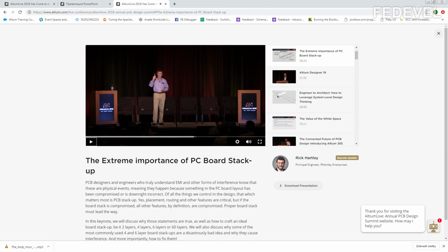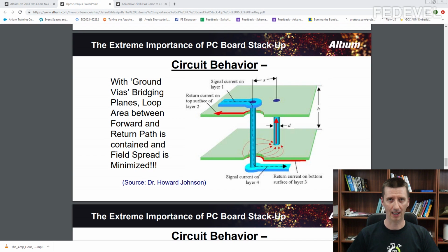Now, what via? This via, which is here. I didn't speak about this via. Do you know what this via is doing? Usually, you will find people call these vias stitching vias. And you will find these stitching vias in the places where high-speed signals are changing reference planes.